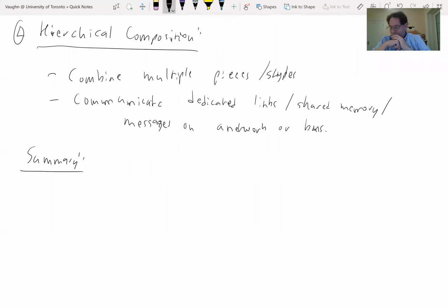I guess I'm not going to write this down, but my summary of this would be, we looked at a lot of different programming models. The ones that are kind of the most hardware friendly tend to be the streaming ones. So streaming is very hardware friendly, can be very efficient in FPGA. It's not the only thing, but to use an FPGA and get good efficiency from it, you don't want to be doing everything with a generic soft processor.